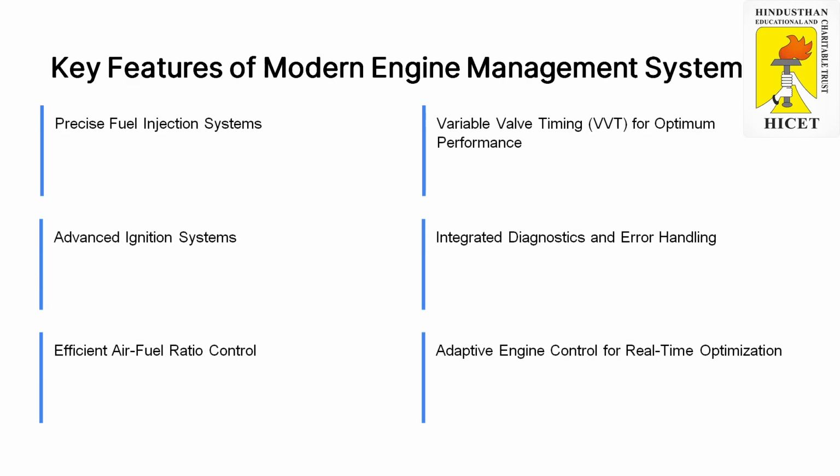Next, the key features of modern engine management systems are, first, precise fuel injection systems. It can accurately inject the fuel, like in split injection and sequential injection. Split injection means, for example, 1 ml of fuel injected into a single cylinder is split into 3 or 4 stages. The Tata Safari Dicor is introducing such a technology. So the precise quantity of fuel injection is made possible.